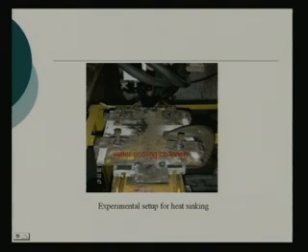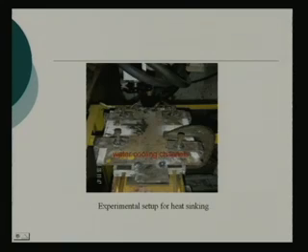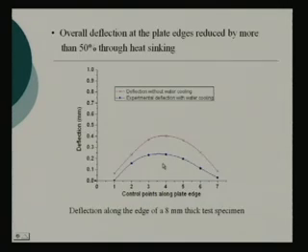There are two channels, right. It is actually replicating this situation: 50 millimeter away from the weld line, this is the weld central line, and a 50 millimeter wide cooling channel. From here, this is the weld central line, and from here it is another 50 millimeter, and the welding was done just to physically verify.